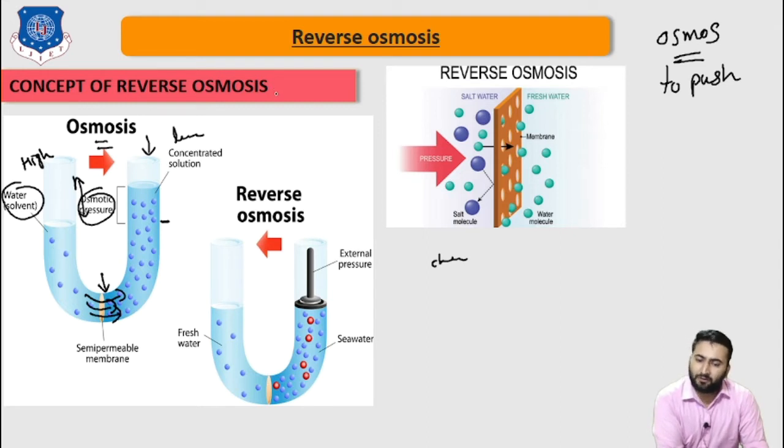Now let's discuss the concept of reverse osmosis. Reverse osmosis, less commonly known as hyperfiltration, is a high pressure, energy efficient technique for dewatering processes and streams, concentrating low molecular weight substances in solution and purifying waste water. It has the ability to remove dissolved as well as suspended solids. RO is widely used in the desalination of brackish water.